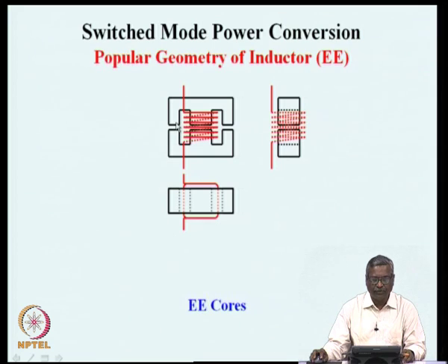As we had seen before, if the relative permeability of the magnetic material is very large compared to the air relative permeability, which is 1, then the shape of the core or the material of the core does not determine the inductance value, and so the design becomes much simpler. This is an E type of core in which a certain number of turns are wound, and you see the views as a cross section, end view and also the top view.